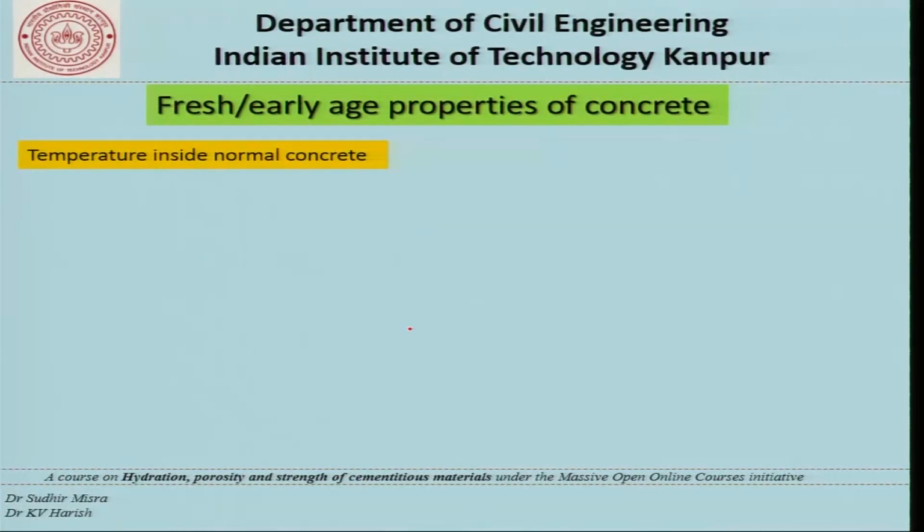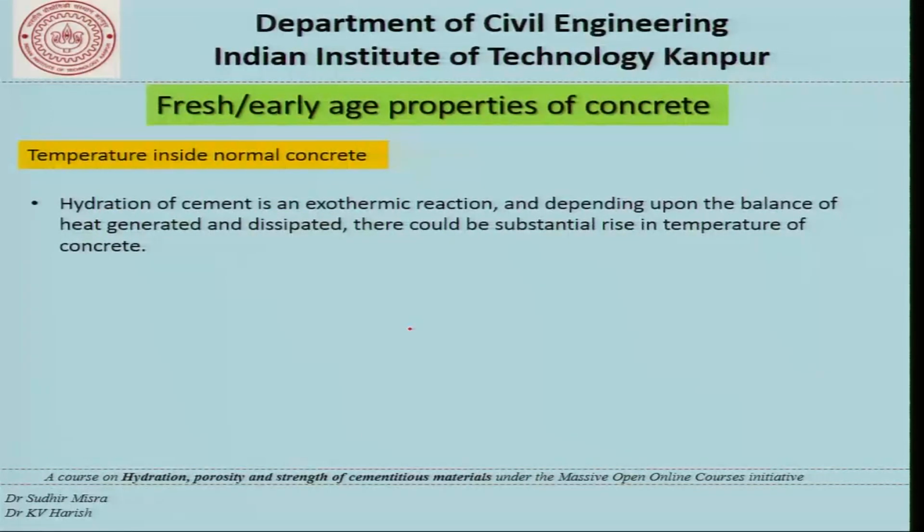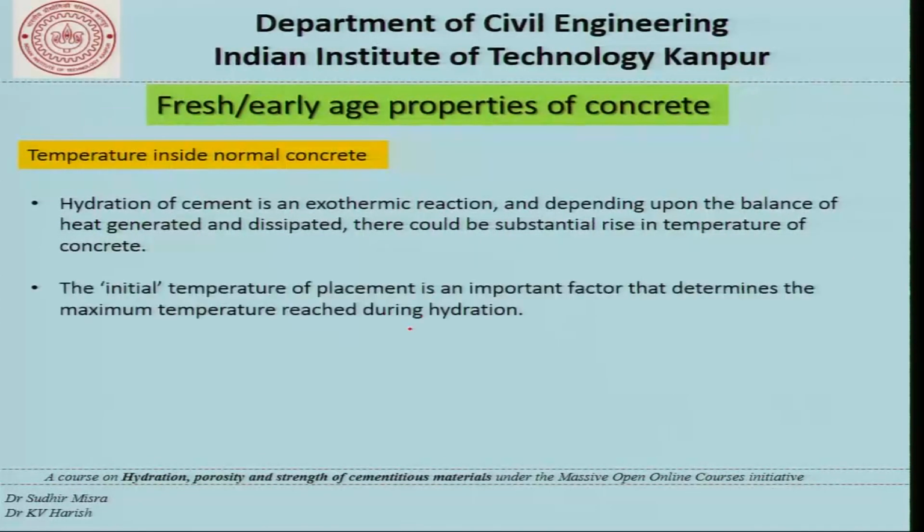Now let's talk about temperature. We must remember that hydration of cement is an exothermic reaction, and depending upon the balance of the heat generated within the concrete and the heat dissipated from that concrete because of the atmosphere, there could be a substantial rise of temperature in the concrete.